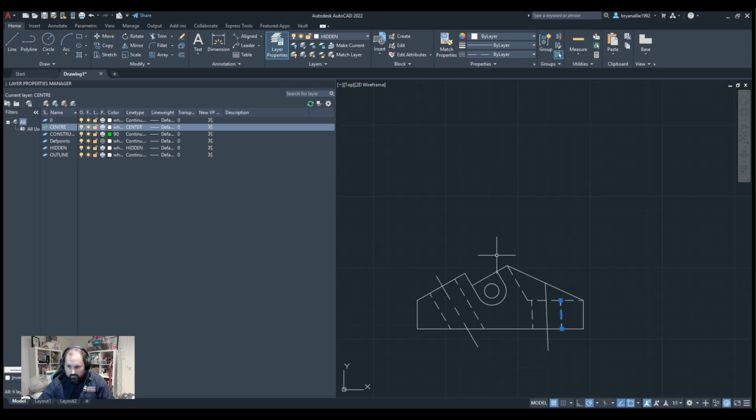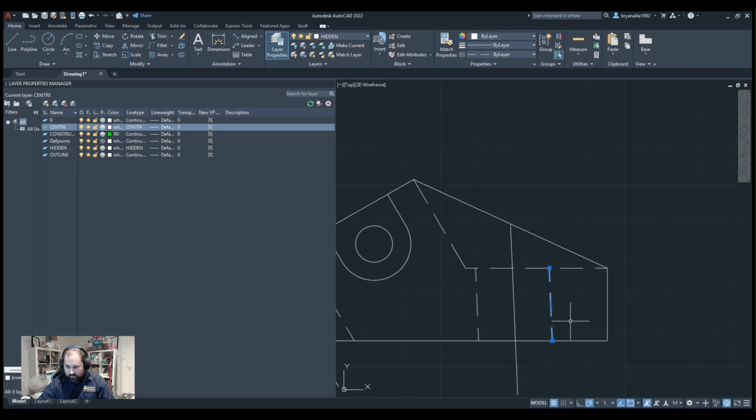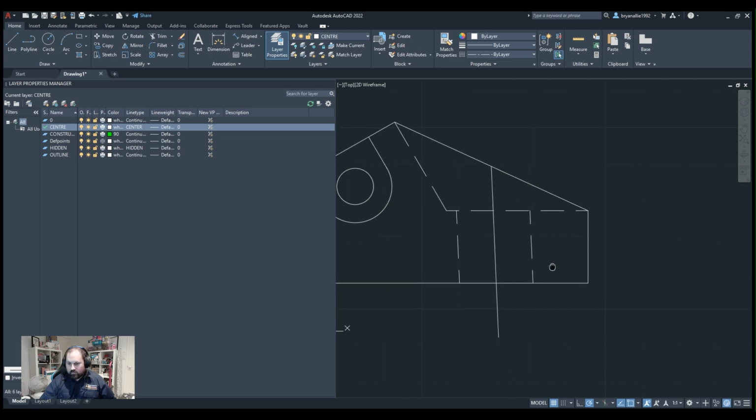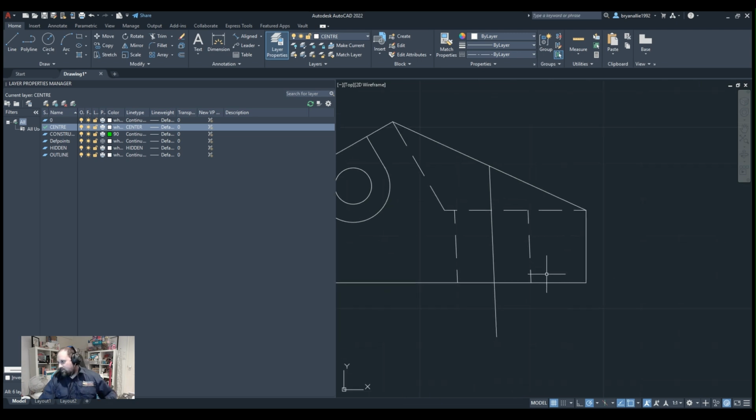trim. Okay, so what we do now is we'll do a hidden line for that 45-degree notch. Now it's on here, it's 45 degrees in, and you got 38 going up on the side. 60 take away 38, 22. So because it's 45 degrees, it'll be 22 both sides.